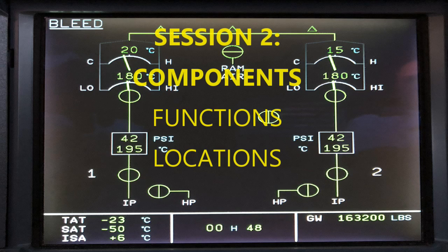So here, the pressure regulating valve is located on the engine at the 1130 position. Okay, it's a butterfly type valve, spring loaded closed in absence of upstream pressure. So just pretty standard. You have a minimum upstream pressure of 8 psig in order to open up that valve.